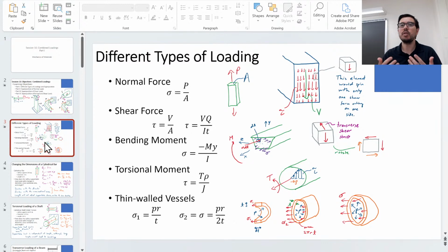And similarly with shear stresses, we might have a tau xy, and we might have a tau yz, or a tau xz. We're not going to be able to add a tau xy directly to a tau yz, but they are shear stresses that are helping to define the state of stress on a material element in a given orientation. Later, we're going to look at these material elements and at how the orientation of these material elements affects the depicted state of stress, or the equivalent state of stress.